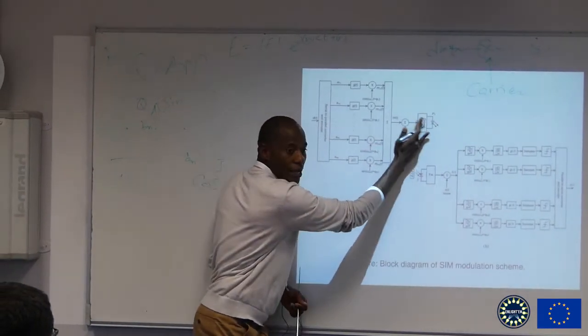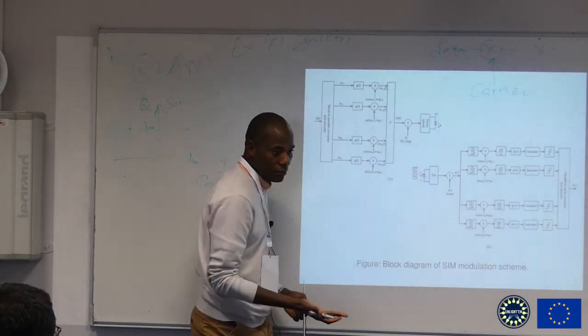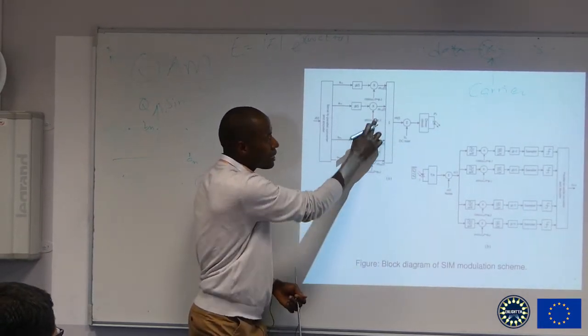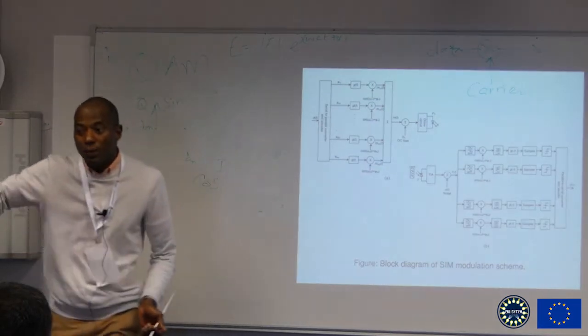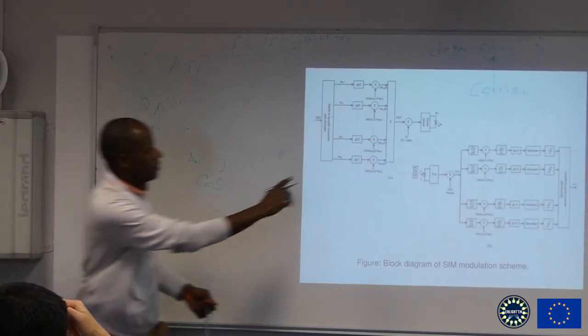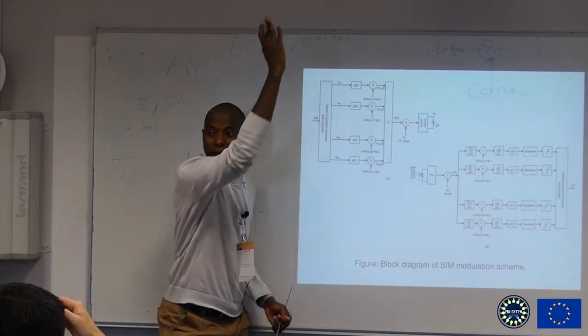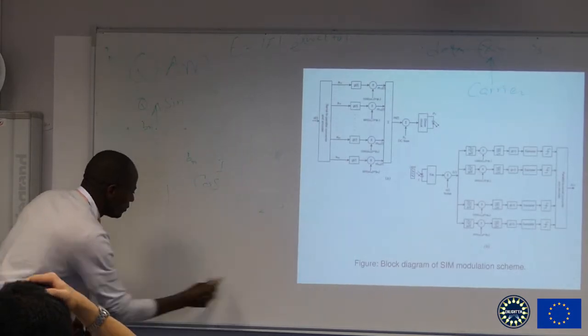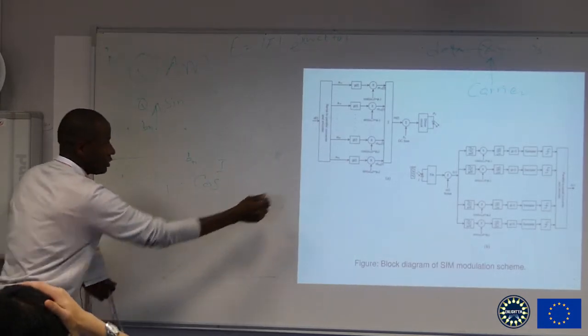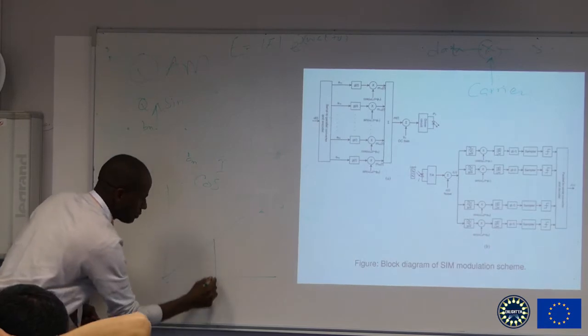And then we go to the front end, as I explained. That's our MT. Because this signal, this cosine and sine, they are still unipolar, so we need some DC. We need to put it at the bias point. If you remember this graph, this DC, this one here, is this point.